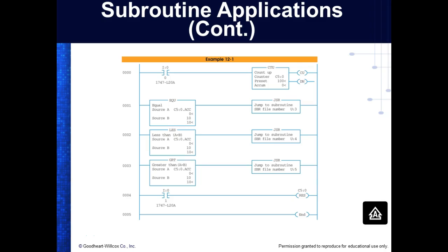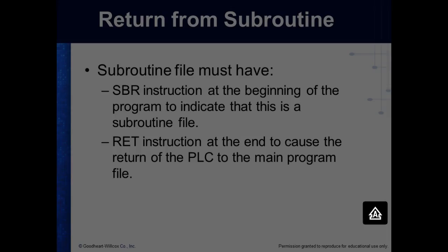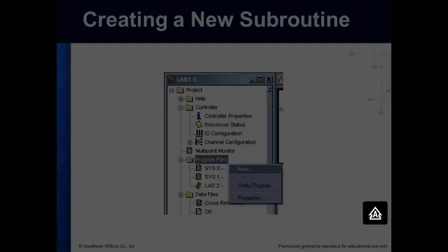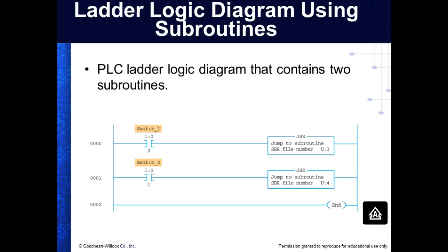If it's on a line without an input, then it's going to call that subroutine every time through the scan. We okay? We do that all the time, especially if we're just going to call subroutines. So if I came up here and did not have a contact in it at all, just a straight piece of wire, this would be what we call an unconditional JSR, which means no matter what, every time it scans, it's going to go off to that subroutine.